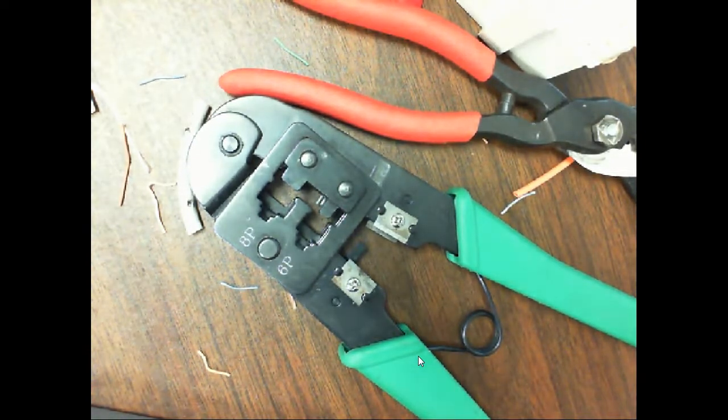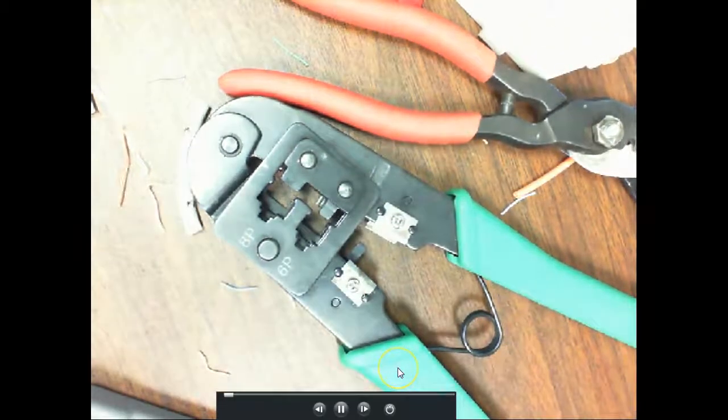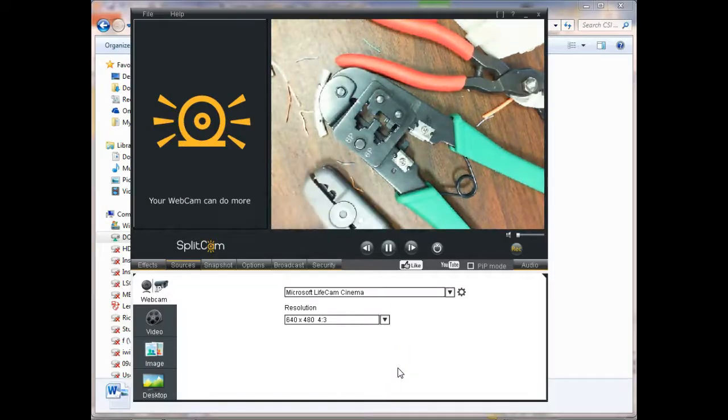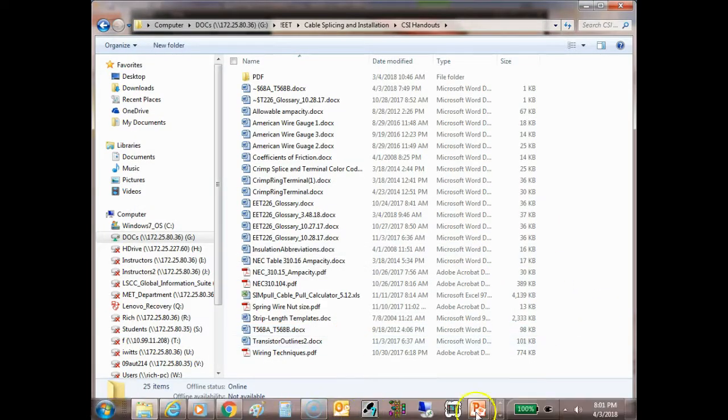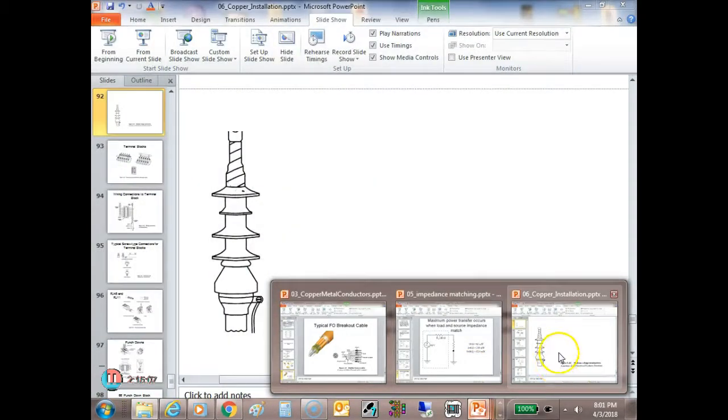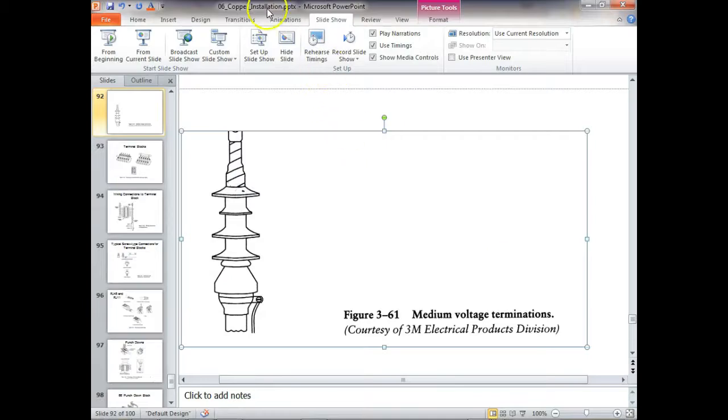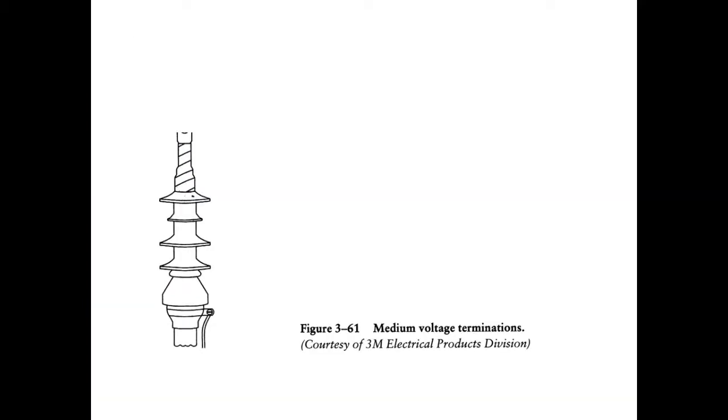What they use is what has really made a difference. We used to send signals using something called single-ended. Single-ended transmission is basically obsolete. We don't ever use that anymore. Single-ended means you reference one wire to common. So what you do is you come over here and you send the wire out.